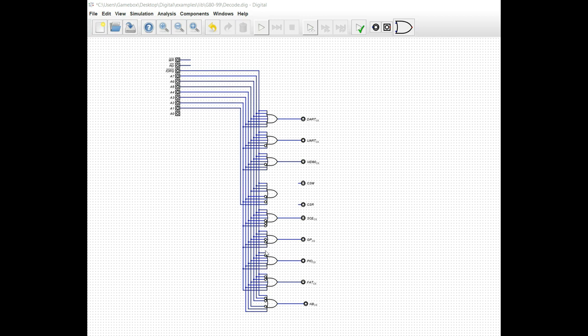We're using OR gates because OR gates and NOT gates don't take up a lot of logic internally. If you start getting into 3-to-8 decoders, it can ultimately end up getting fairly expensive logic wise, but we've decided to use this method. The great thing about that is we can use essentially the same circuit. We just change the input, whether it needs to be high or low, and as you can see I've done that with several of these.